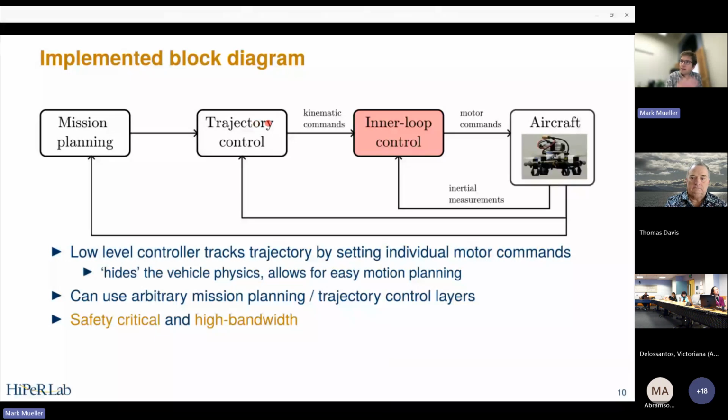I think in the experiments we were showing, we give it acceleration limits, not velocity limits or anything like that, because we're only evaluating it for relatively short motions that were not too fast, so the velocity did not particularly matter. But if you were doing something where you're moving at high speed, you probably want to add additional limitations to it, yes.